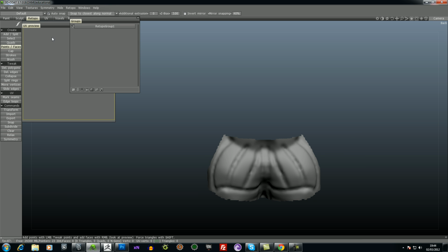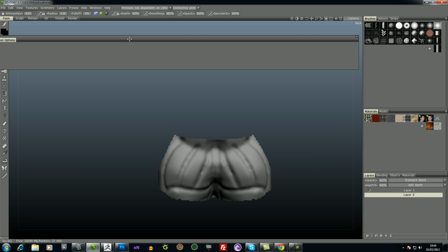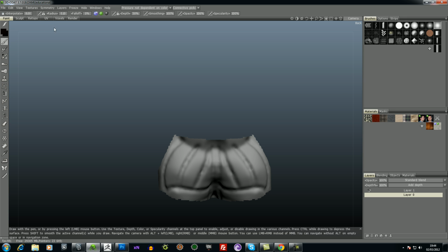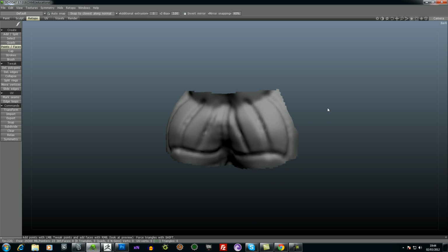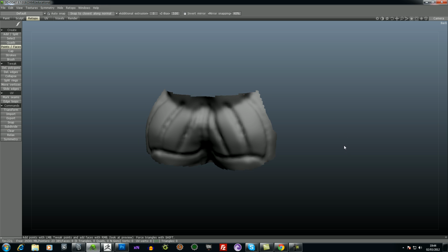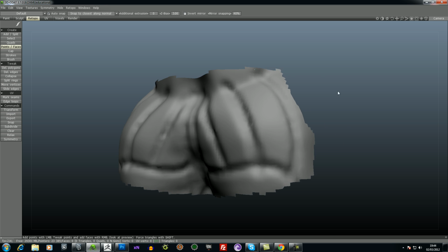Click on the retopology tab there, and it kind of jumps up because I've got this all messed about. I really don't need that there at all. I could do with cleaning this up. The way all these windows keep appearing is really annoying. Right, so I'm using the mouse buttons, middle mouse button, left and right to navigate here in 3D Coat. Middle mouse button pans, left to rotate around and right to zoom in and out.